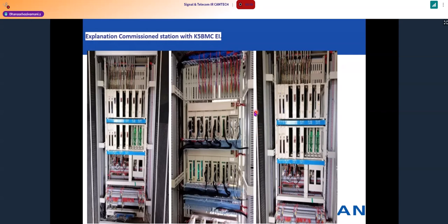And 110 volt AC is coming in on one side, and on the other side 24 volt DC is coming in the other trough. So 110 volt and 24 volt will not mix. They will be coming in opposite directions. 110 will be terminated in the back side, and 24 will be terminated in the front side. So it is possible now that 110 and 24 will not mix. We design in such a way that 24 and 110 should not mix.